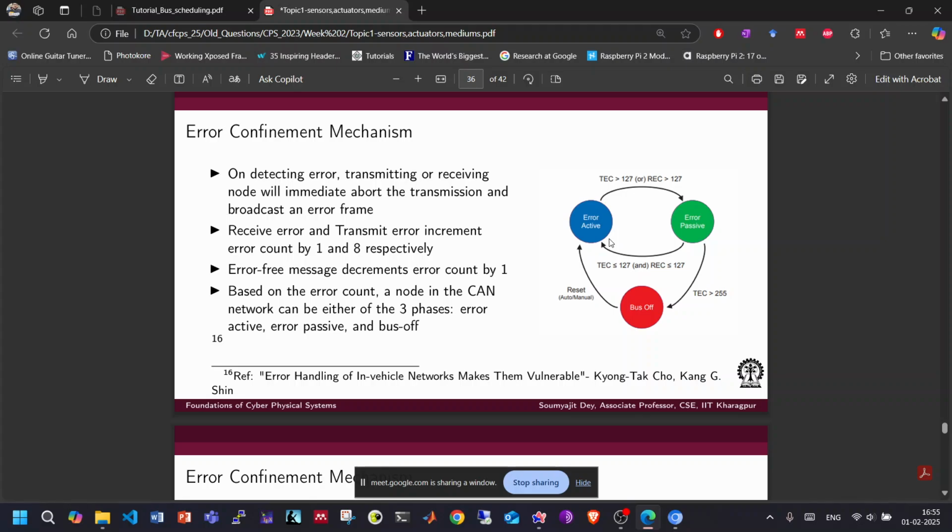There are many vulnerabilities in CAN, not only this, there are many drawbacks in CAN, I should say. One drawback that you will find if you compare it with other protocols, maybe with Ethernet, is that in Ethernet we can understand different entities by seeing their IP addresses, right? But in CAN, you don't get to see from which entity I am getting the data, because it is very simplistic. Anyone can send any data.